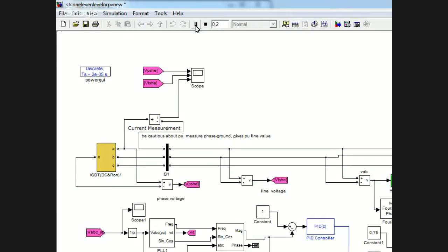So in this system, if you see what we did, our main aim was to reduce the harmonics, so we wrote the equations. After writing the equations, we solved them. We can solve them using any method: Newton-Raphson, GA, PSO, any method. The one which I showed you now, I have solved using PSO, and I got those optimal angles, and those optimal angles I have implemented here using a neural network.